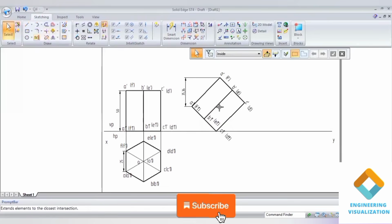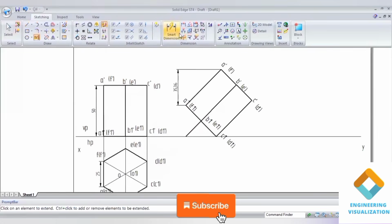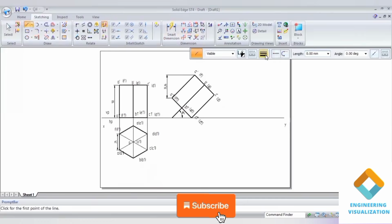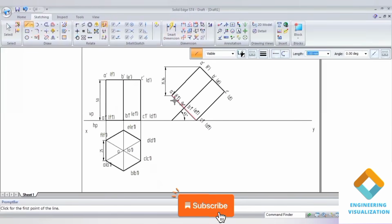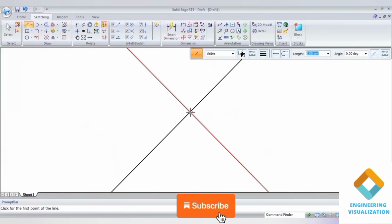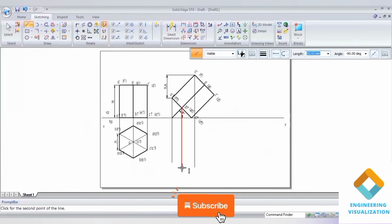Okay, now extend the axis, find out the angle and project downward to complete the second position, top view. So draw the projection line downward here. Draw the projection lines downward to complete the second position, top view.